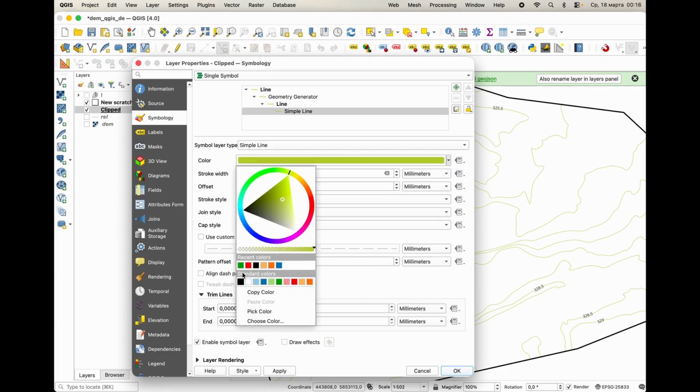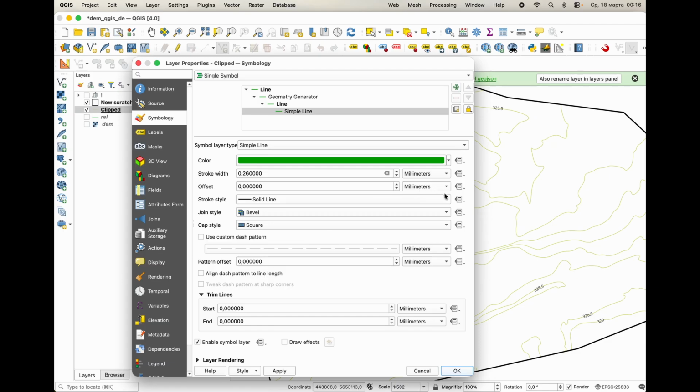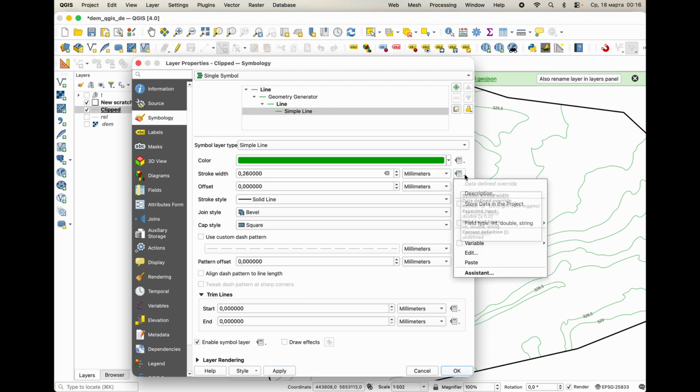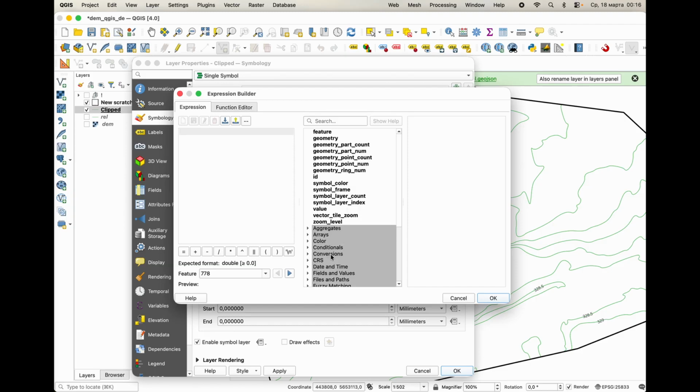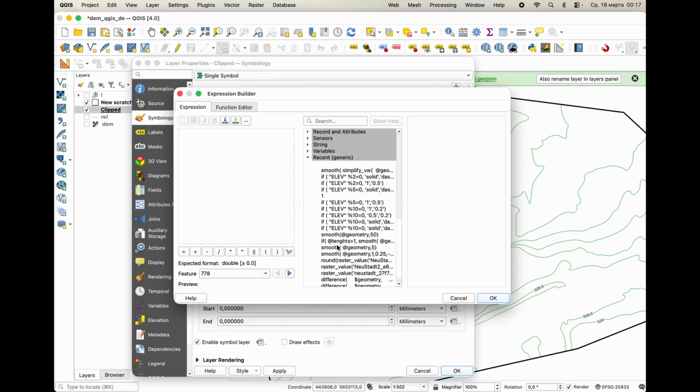This is especially useful in denser areas where many contour lines are close together. We can also apply some slight visual smoothing or refinement if needed, depending on how the source data behaves and how clean we want the final map to look. Again, the goal is not to distort the terrain, but to make the representation more readable and easier to communicate.